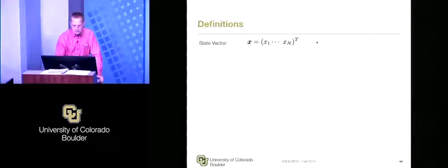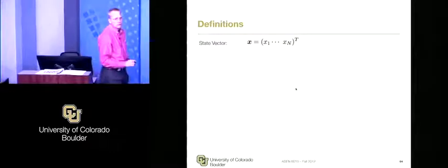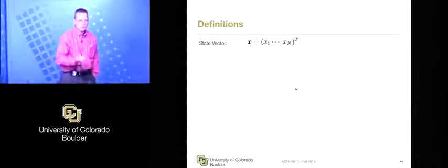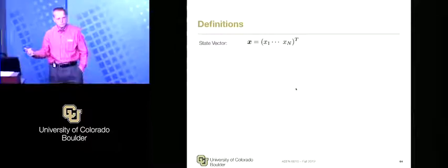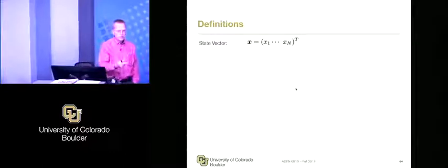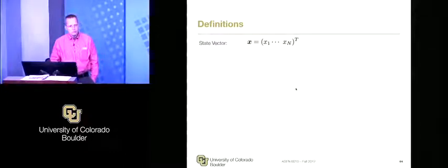The state vector. What is that? For the attitude problem, purely rotational kinematics, Benjamin, what goes into the state vector? For rotational kinematics, I would put the attitude angles. So MRPs, for example, sigma 1, 2, and 3. What else? Quaternions. You would put MRPs and quaternions? No, I mean one or the other. Okay, so we picked one. That's it?